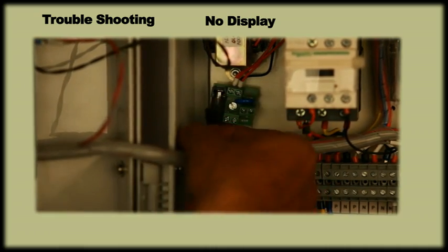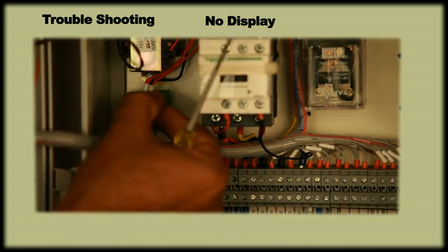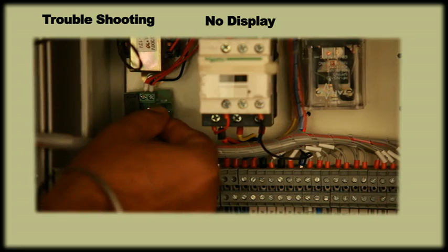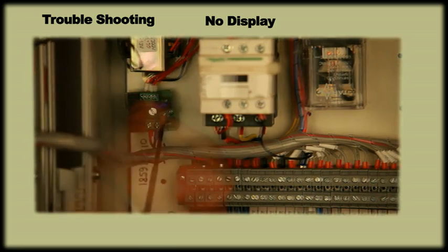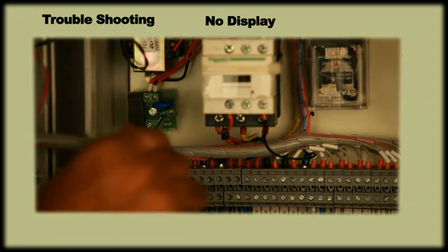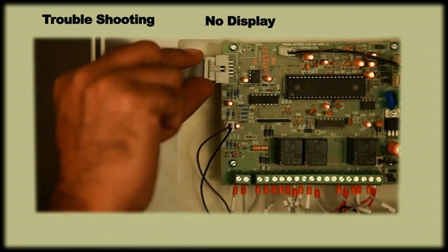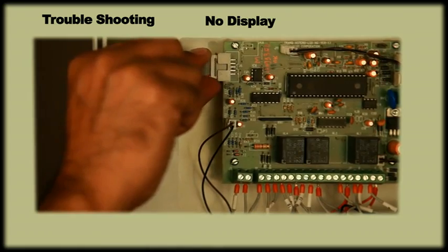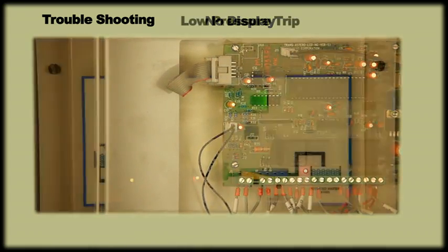Switch on power again. If it burns again, replace the fuse as well as the MOV of 320 volt. If the fuse is OK, check the FRC for loose connection. If it is loose, reinsert it properly.